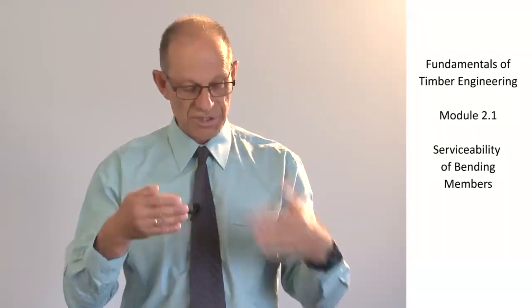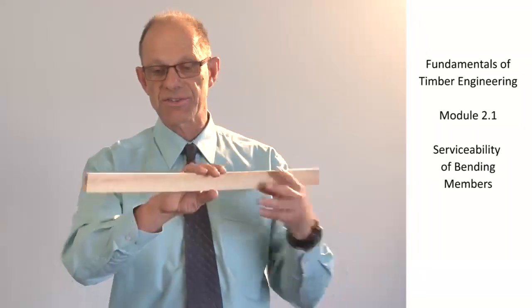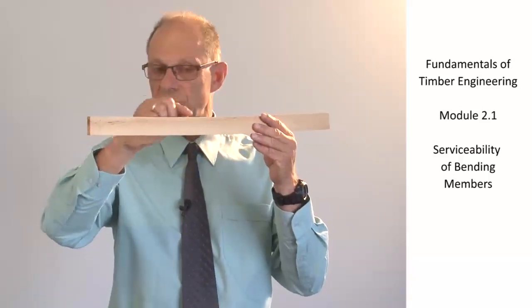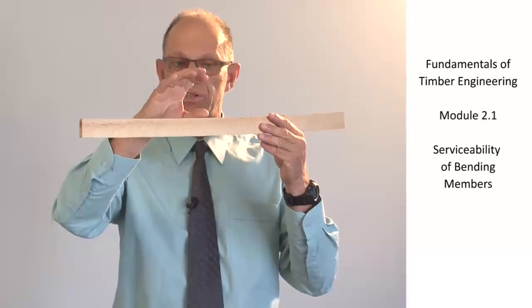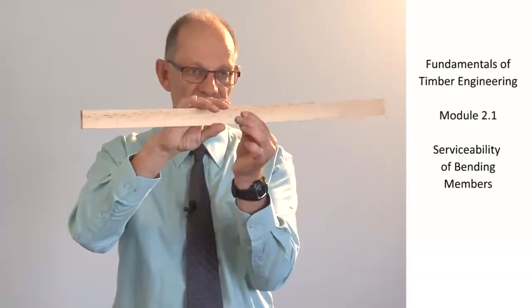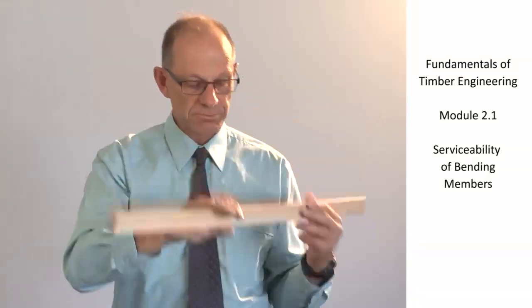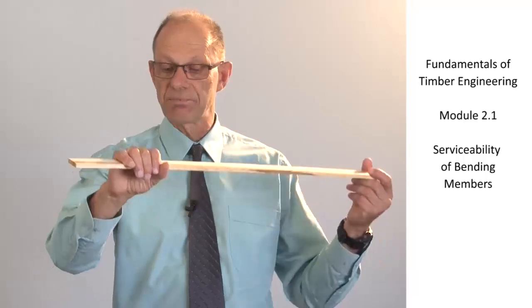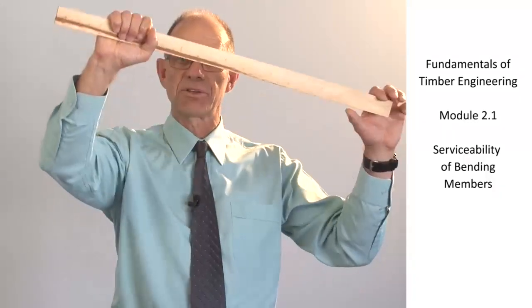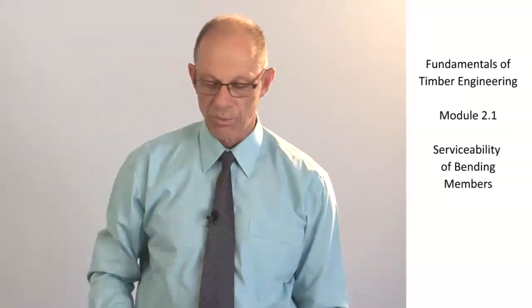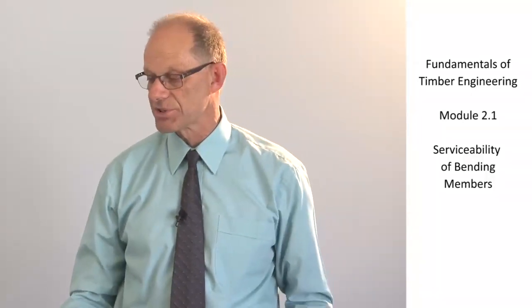For example, if you're designing beams underneath some rotating machinery and that beam deflects too much, it can cause the rotating machinery to malfunction. So there, that beam would have a very tight deflection limit. In other cases, it doesn't matter too much whether the beam deflects. This is typical of roofs, where we can accommodate a little bit of deflection without causing any structural problems at all.